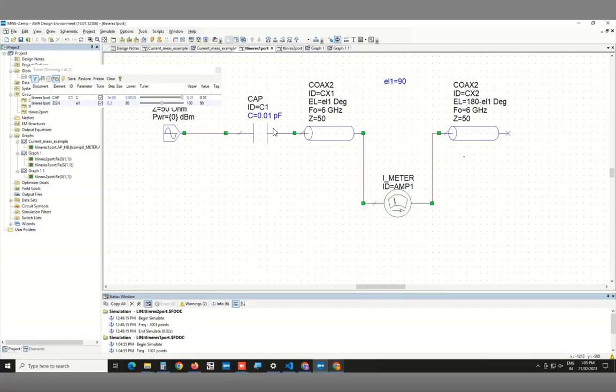If you have a pipe of a certain length, like a flute, then that has a resonant frequency. But at the boundary, when the flute tube ends and reaches the air, there is an impedance mismatch, but it's not a perfectly sharp boundary. So it looks like the actual length of the tube is slightly longer than the physical length. Similarly, this capacitor adds extra capacitance and lowers the frequency, which is equivalent to having a longer transmission line, right? If you had a longer transmission line, the frequency would be lower as well.